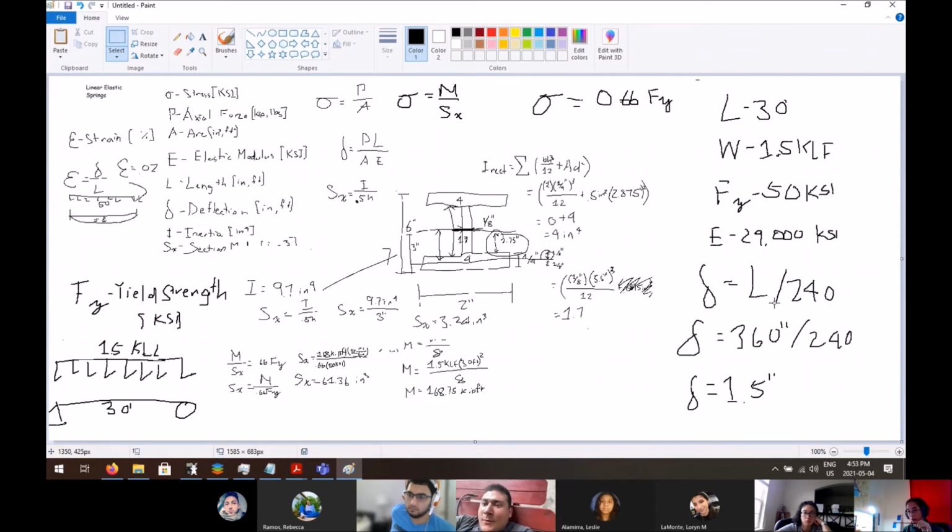Like you have this beam, which is a certain distance across, and using this formula, you can determine exactly how much your deflection allows it to go. Right. Okay, because I saw a 360 against a 240, and then you said it was 1.5 inches. I thought that would be 1 foot, 1 inch, something like that. No, so it would be 360 inches divided by a unitless 240, so it doesn't change the units, right? Ah, okay, now I get it.